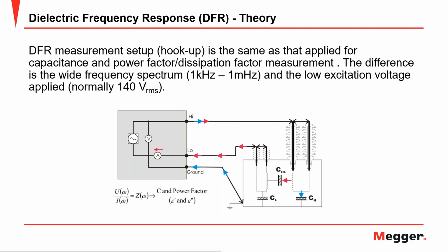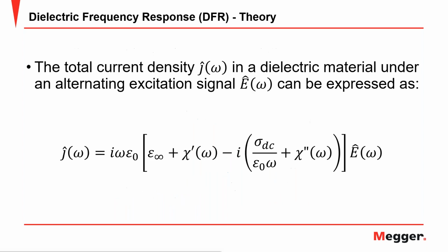The idea of applying 10 kV most of the time is to overcome the influence of noise in the substation. But otherwise, because we're talking about a high capacitance on your transformer, 200 volt is sufficient to get a very nice response and to measure the power factor value, unless a voltage dependence is detected in the insulation, and that's something that was highlighted on the previous presentation.